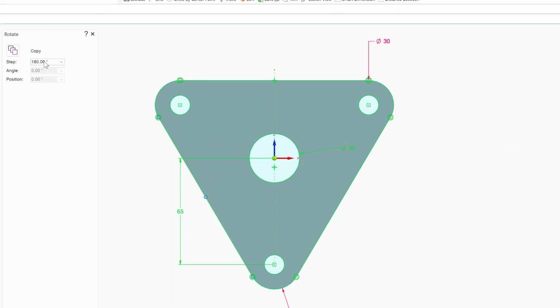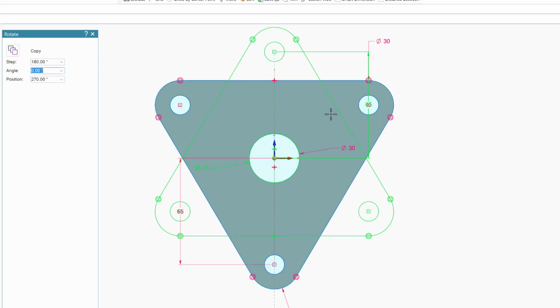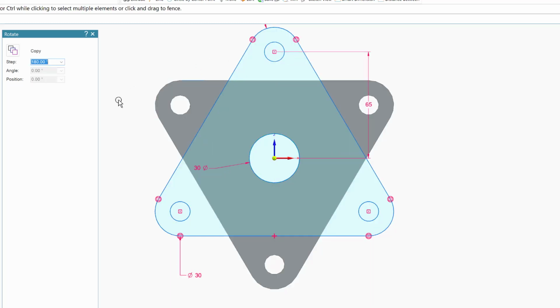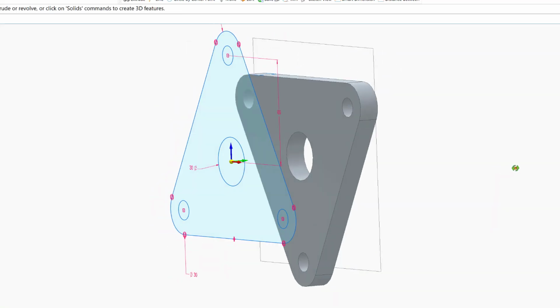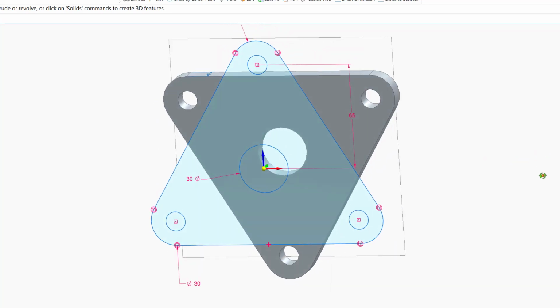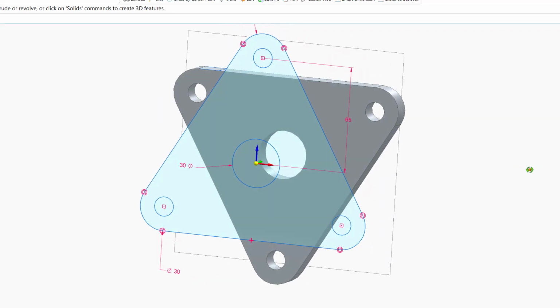So now I need to go to the center of the circle here, and go vertically down to one of the points here to the center here, and then rotate this one to the top. Since it is 180, automatically it will go 180. So I'm going to click, okay, and escape to get out. So this way I was able to rotate the sketch, how much? 180 degrees. So this way it becomes in front of the other one.